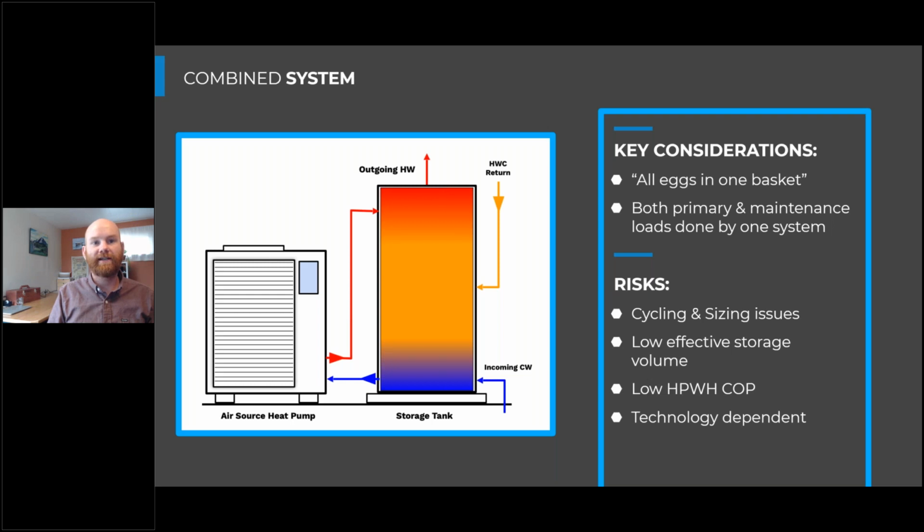So when we have multiple tanks and they're parallel, balancing through those tanks is really, really critical. And I noted that in session 1, because otherwise we can have a tank that drifts in temperature away from the other tanks in our parallel group. So we have to be aware of that. With a multi-pass heat pump in this combined system, yes, you'd be leaning towards that parallel tank design. And then that hot water circulation needs to be balanced across all those tanks, as well as the cold water and hot water flow out, and the heat pump entering water and leaving water flow.